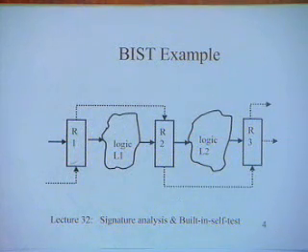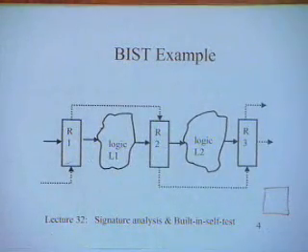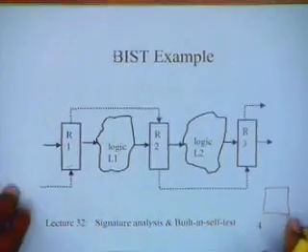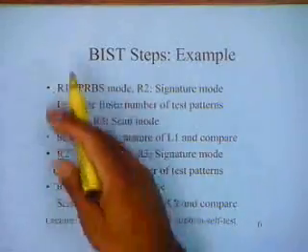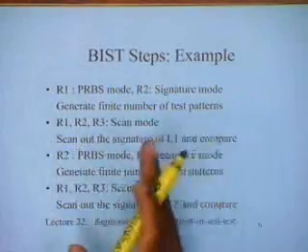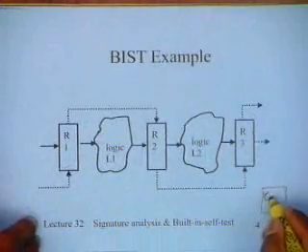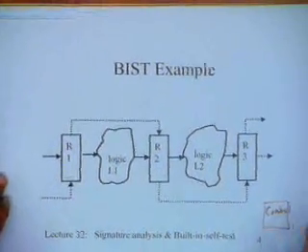Third, this is a completely built-in self-test type of situation. You have to have some small memory and control logic, which will take control during the testing, because during the testing I have to generate these sequences. There will also be a control that is required which is different from the control during the normal operation. So I have to have this control logic, as well as some test results stored.